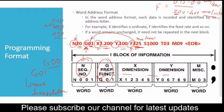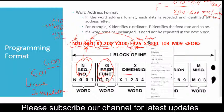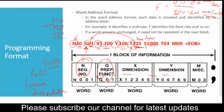Now the 1000 is preceded by what? S. S stands for spindle RPM. So the chuck will rotate, or the workpiece will be rotated, at 1000 revolutions per minute. Now the next is T03. Does 03 stand for a number? The 03 is preceded by T.